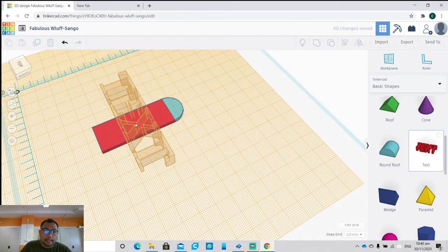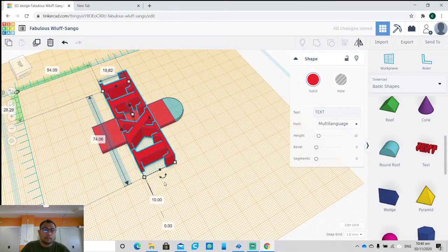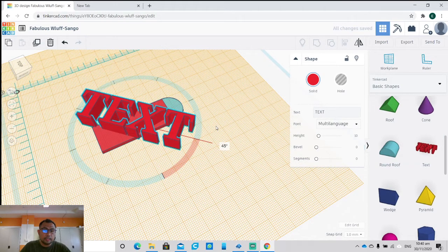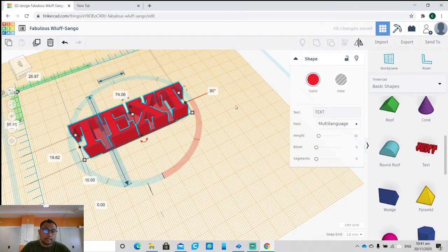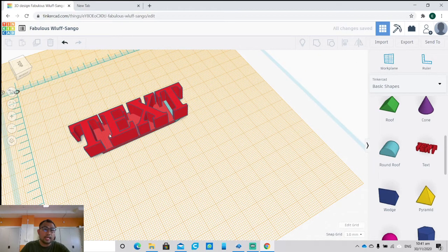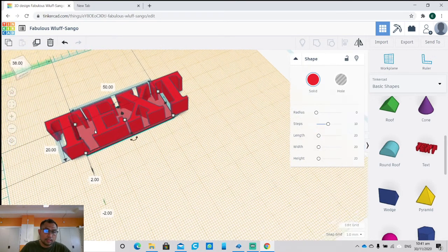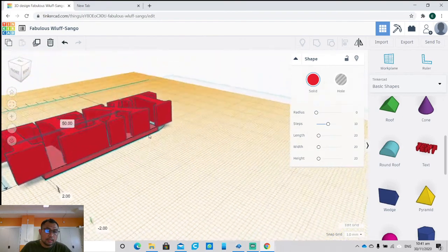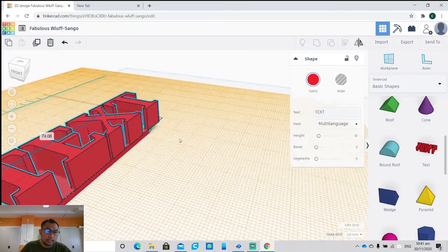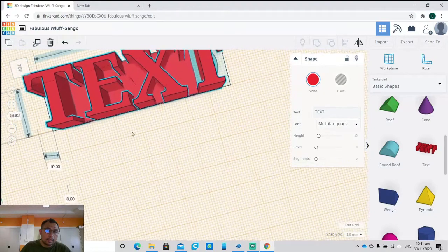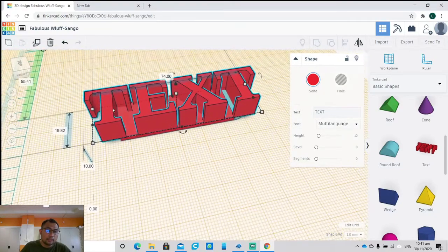And click on text. Now I am gonna rotate the text again so that the alignment is aligned with the bookmark's orientation. So this text is too big. Obviously it's too big, so you're gonna click on the text handle spots here.